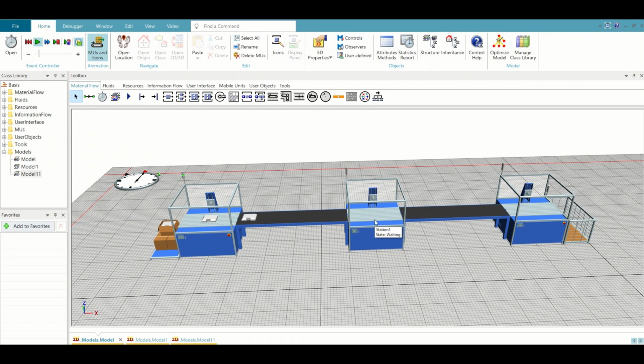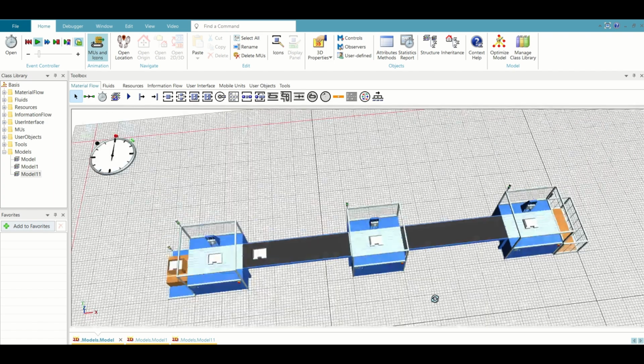This is the easiest way to connect conveyors without having any connections, just like we have it in Flexsim, right? In Plant Simulation, it's quite easy and effective to connect the stations to each other. Now once you have connected these two stations effectively, you can see the part has started flowing onto the conveyor to different stations, right?